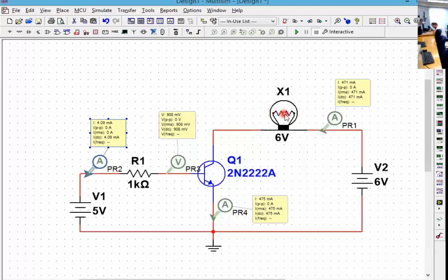But the lamp still doesn't turn on, because the current it requires is more than 471 milliamps. Previously it was like 645, something like that. If you apply that resistor on these, that affects the current going through the collector? Yes, to an extent. Not all the way through, to an extent. But how did they say that it has two different currents?